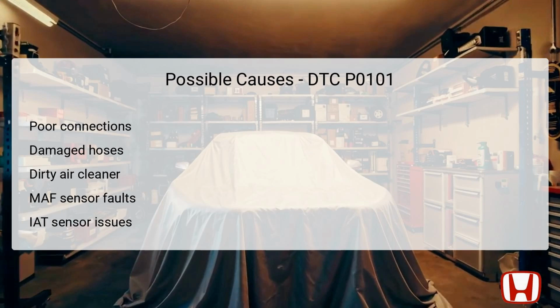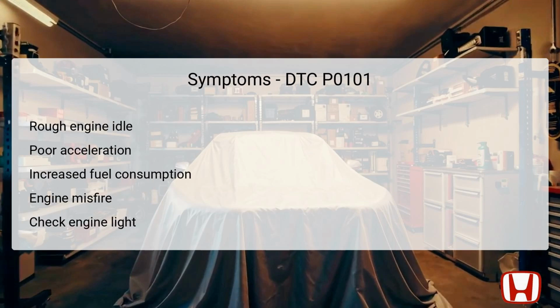Malfunctions in the MAF sensor itself or associated components like the intake air temperature IAT sensor can lead to incorrect data being sent to the powertrain control module PCM, resulting in the DTC being triggered. The symptoms associated with DTC P0101 can vary, but commonly include a rough engine idle, which may cause instability when the vehicle is at a stop.